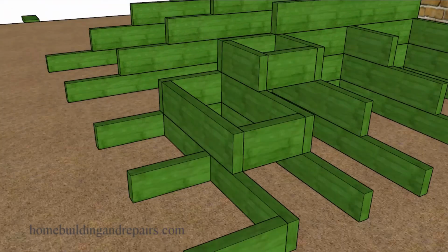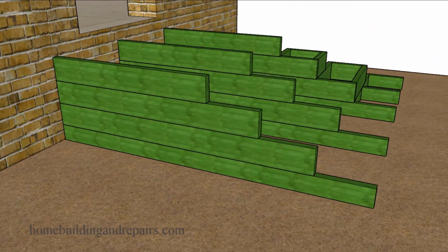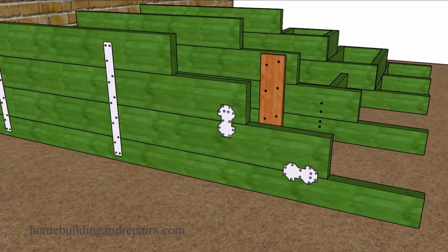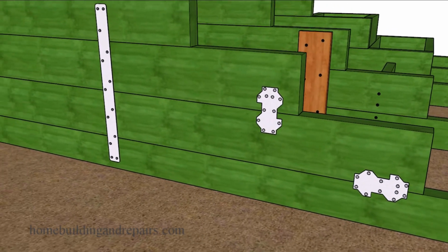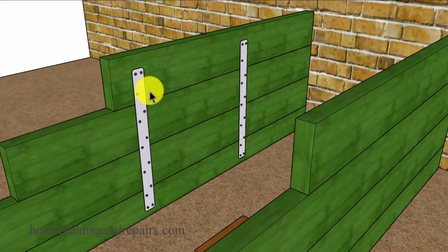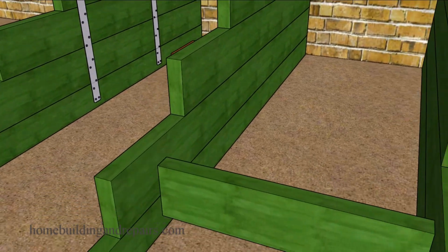And don't forget that you can modify this design, like I mentioned earlier, by installing additional bracing, blocking, and structural supports. And you can connect each one of the 2x6s together with building hardware like straps or flat framing anchors, even blocks. Just make sure that you install some of these framing anchors on each side. If I was just going to install all of these framing anchors on this side, along with the straps, then it might allow the 2x6s to fold over at the breaks or where the 2x6s are going to be connecting to the other 2x6s. So we're going to need to install some type of support bracing on both sides.